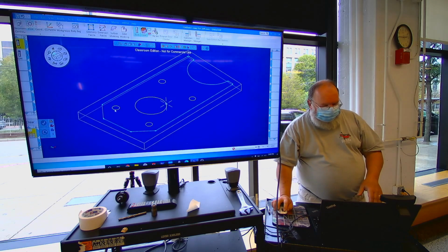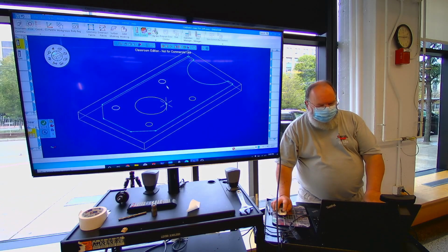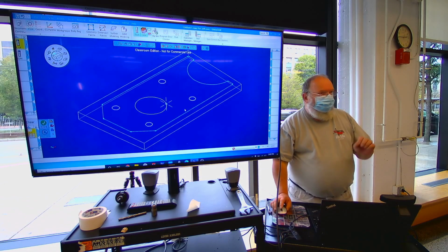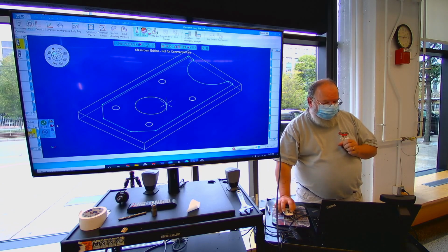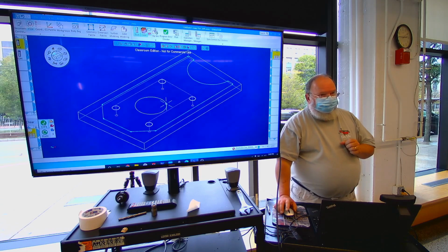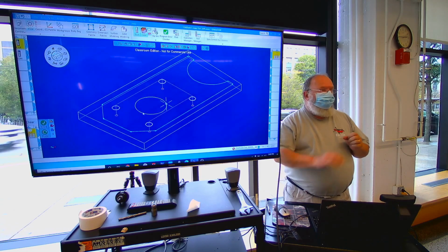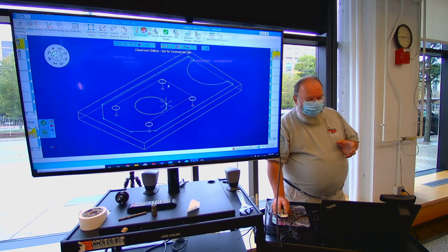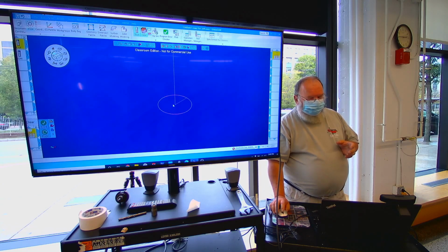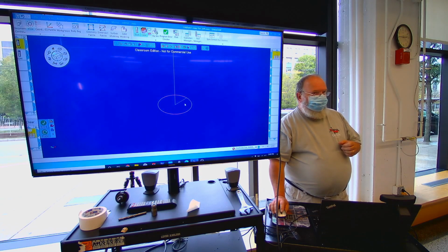So now with everything satisfied, I'm going to go in and I'm going to select all the locations that I want this to happen. And when those are selected, Gibbs gives us a really nice high-tech term to execute these processes called do it. So you see a dashed white line, which represents all the rapid traverse moves. And my actual machining path is this orange. Drive to Z depth in the center, feed out the radius, cut a circle. Okay?